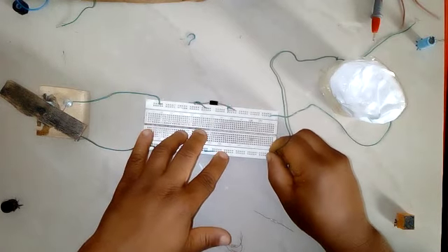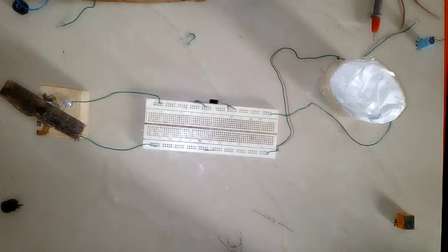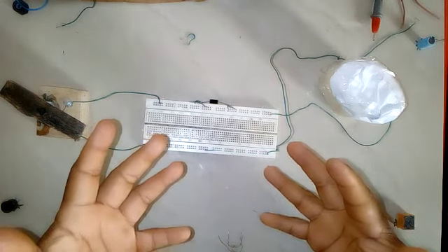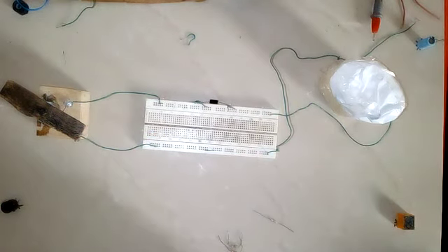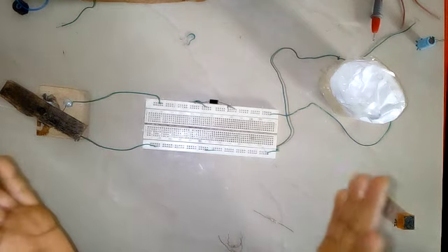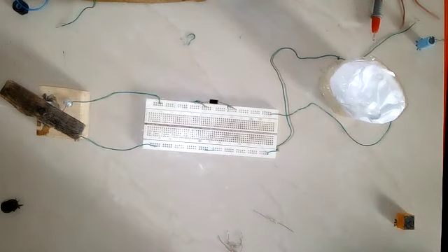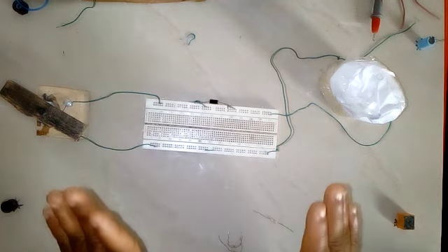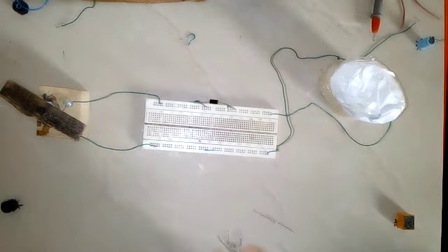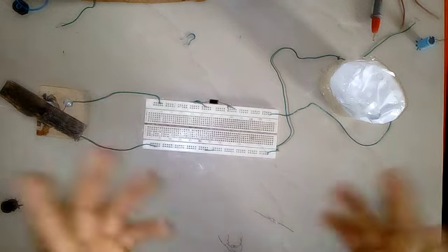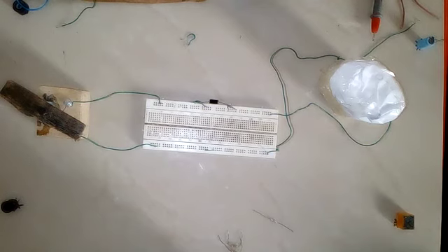It does not turn. What is happening is that because the diode allows current to flow in only one direction, if I reverse the terminals, it blocks the current from flowing in the other direction. What it means is that the diode now presents itself as a very high resistance, almost infinite, so that only minority currents will flow, which are not enough to turn this device on.